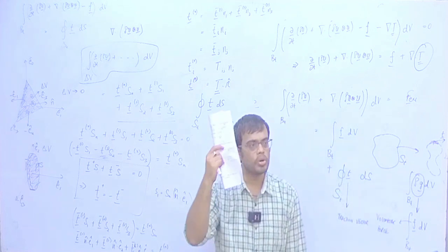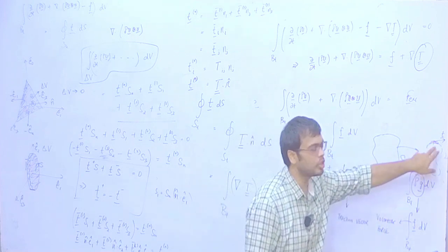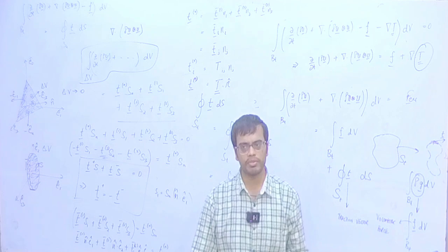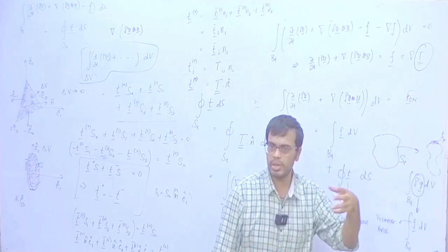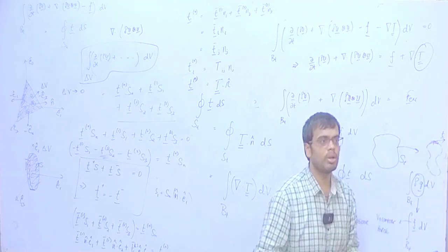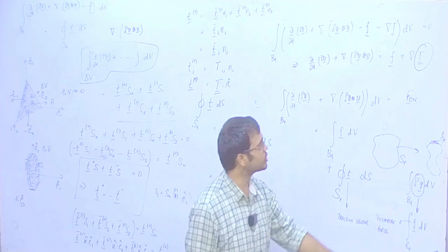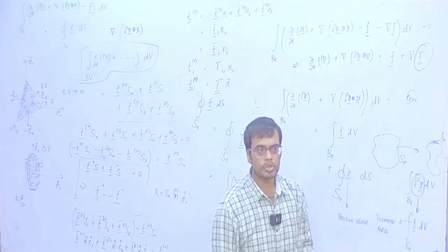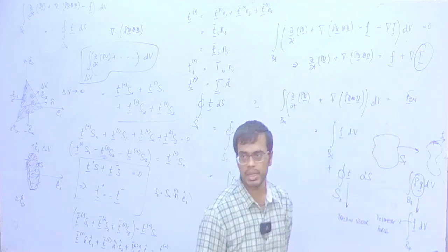So, those of you who know how friction, or let us say how intermolecular forces work, you know that this is going to be the interaction of this blob with the surrounding. Whether both are the same fluid or different fluids does not matter, as long as both are some fluid and one is not vacuum, you are going to have some interaction between the two, and that is what the molecular or material properties of the fluid will determine. So, this T tensor or this small t vector, the traction vector, will have those material properties in them. Rest all are kinematic and dynamic properties.